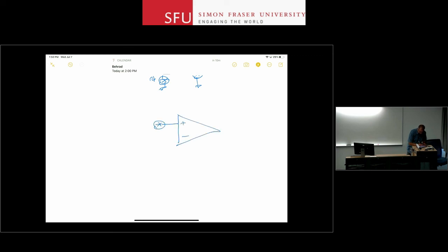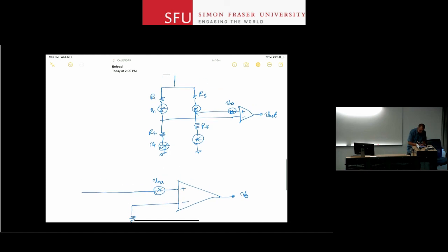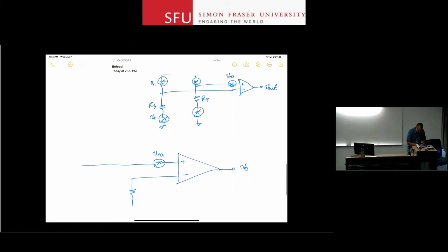Let me put my amplifier noise source here. This is where I'm measuring it. And on each one of these inputs, I combine the two resistors. So let's say R3 here, and let's say R2 here up high for the Wheatstone bridge to provide maximum sensitivity. Okay, so then what I can see is that I can put R1 in parallel with